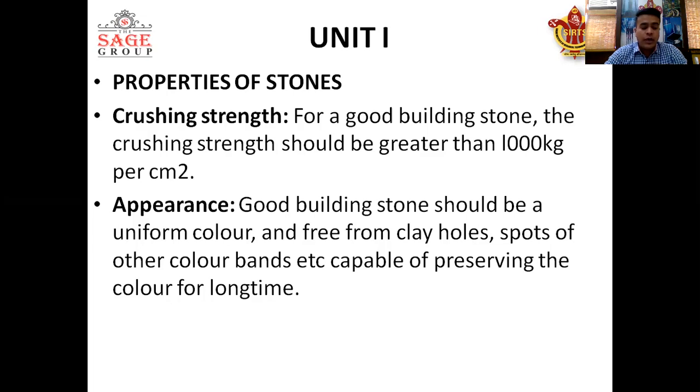Second one, the appearance. A good building stone should be of uniform color, free from clay holes, spots of other color, and bands, and capable of preserving its color for a long time. That means a good building stone has the quality of uniform color throughout its body.